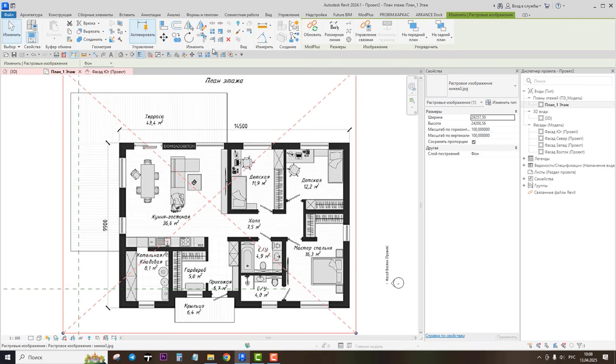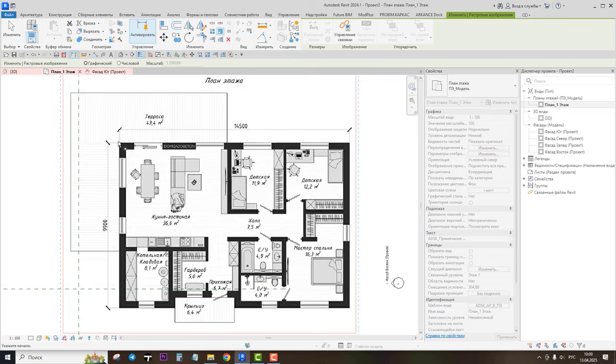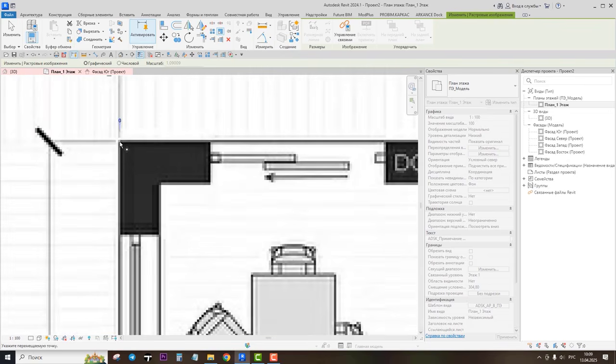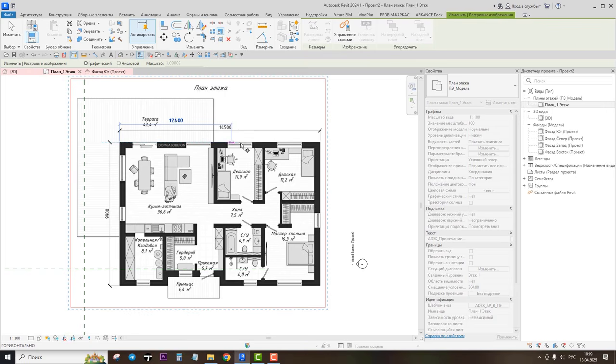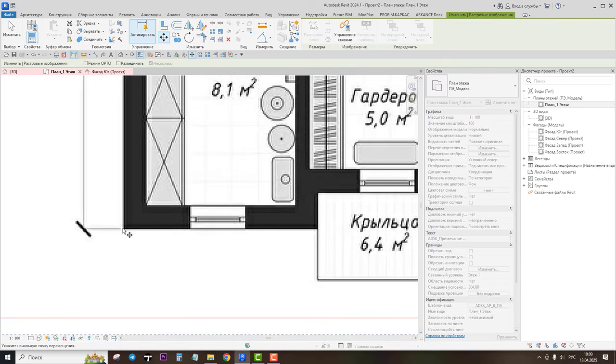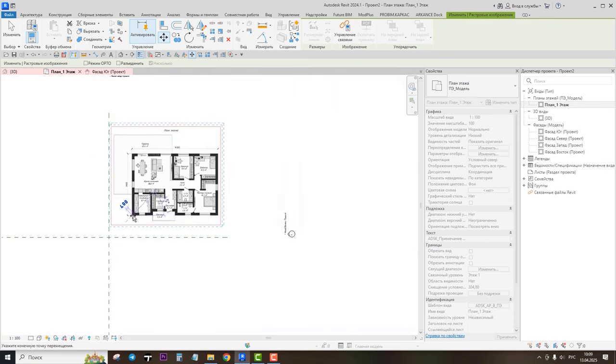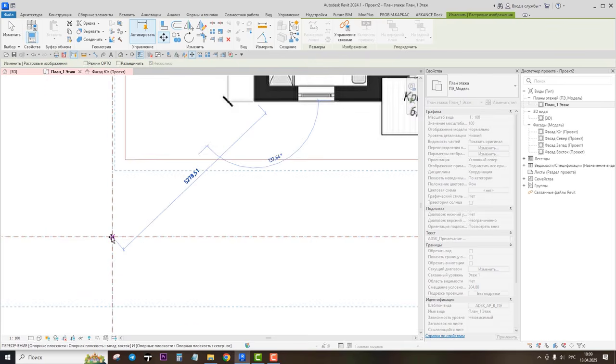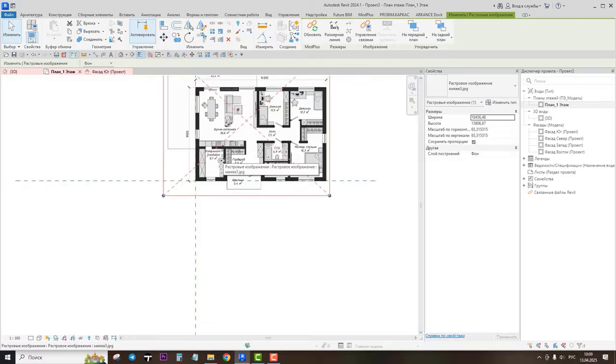Select the picture, the tool Scale, scroll it closer, click on this corner, make the line from this corner to the opposite one. Now it's 22,000 millimeters, but it should be 14,500 millimeters. So left click, type 14,500 and press enter. Okay, we made it smaller. Let's move the picture, choose the tool move and move it to the origin, to the 0 point, okay?